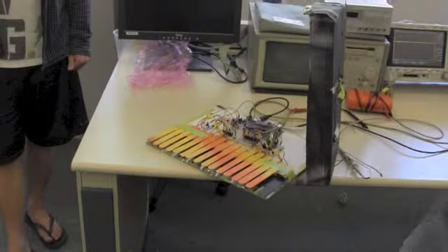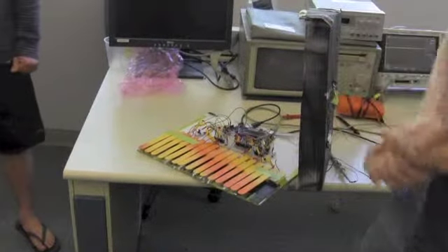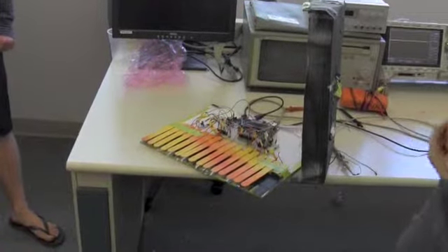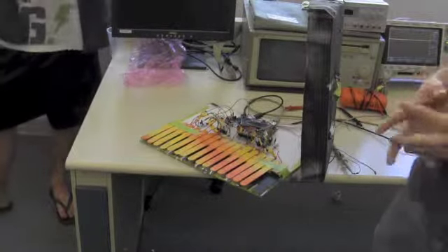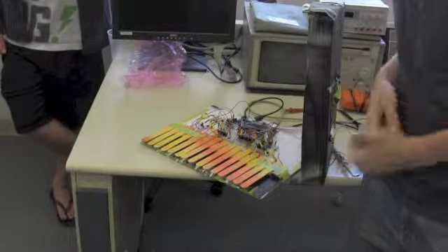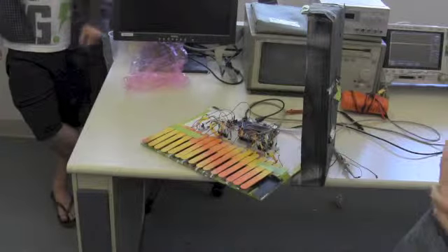Initially, we had an additional key, as you can see here, but we took up too many of the pins on the Arduino over here. We tried to implement the ADC functionality, but it messed up our clock, and we got some really weird electronic noises. It was cool, almost like an electro rave kind of vibe, but that's not really what we wanted for this. So we had to scrap that idea, and instead we had to lose one note of precision, but we're still able to get the full 2 octaves, so I'm not too unhappy about that.